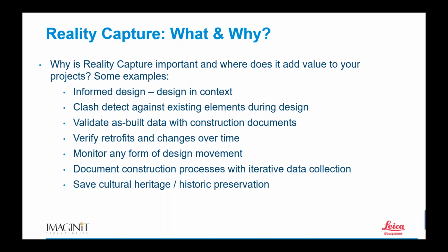I've got clash detection, utilizing the point cloud data captured from photogrammetry or whatever device we're using, taking that and overlaying it with the model, doing a clash to see if my piping or my conveyor system or whatever I'm designing can get from point A to point B. So, virtually comparing the as-built conditions point cloud with the new model.